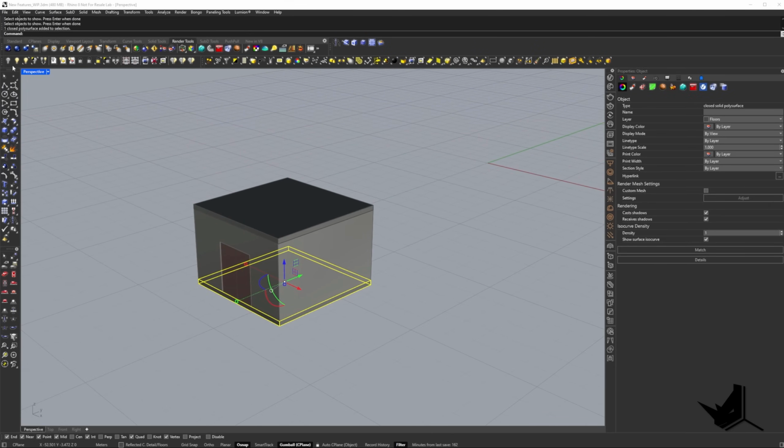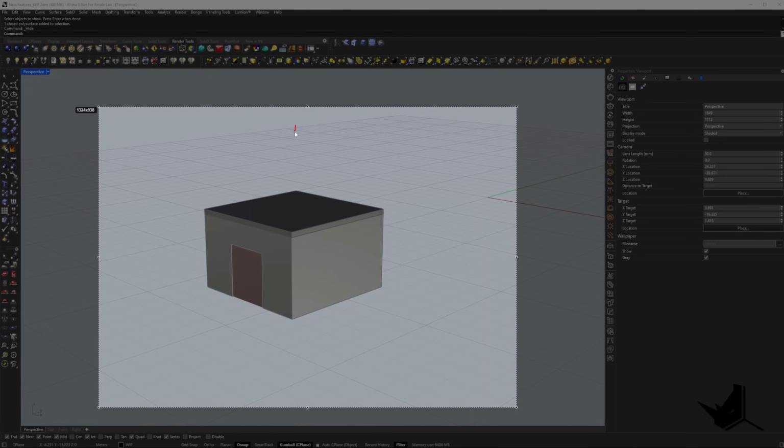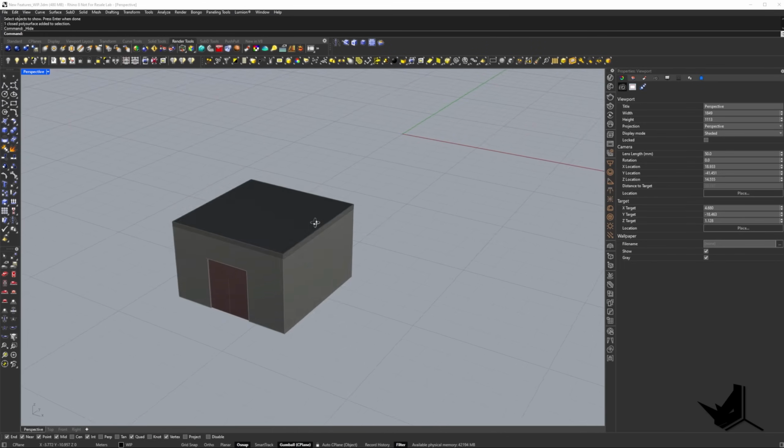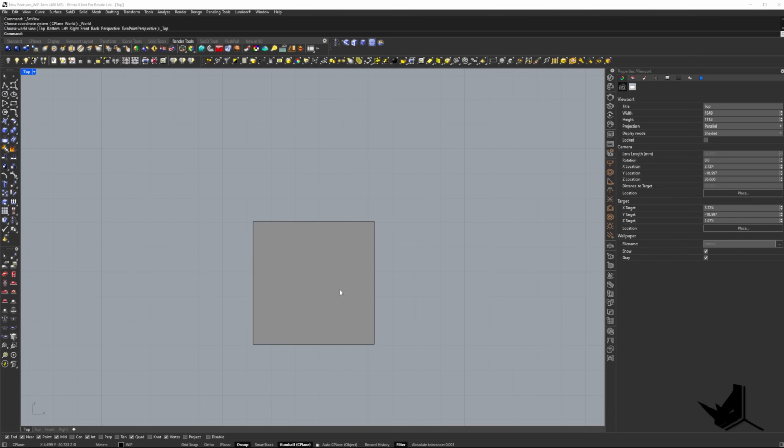reflected ceiling plan. Reflected ceiling plan works just like you have, for example, the top view in the Rhino viewport. Reflected ceiling plan allows you to look at your model from the bottom, exactly as it's supposed to be. That way you have both drawings that you can use for the base plan and also for the reflected ceiling plan. The way to activate this, for example, is to go to the top view. So I'm going to go to the top view here like this.